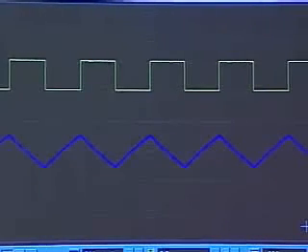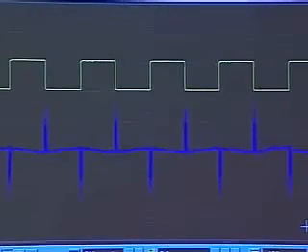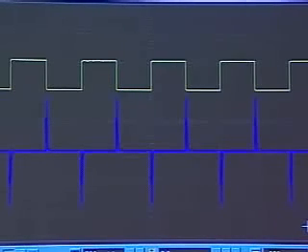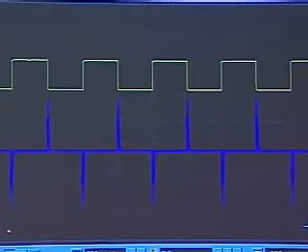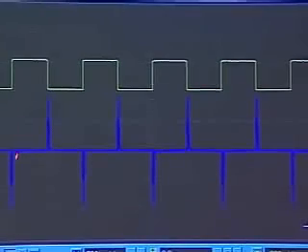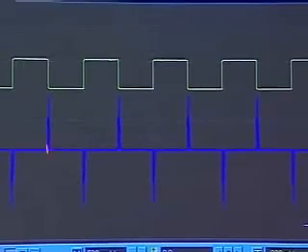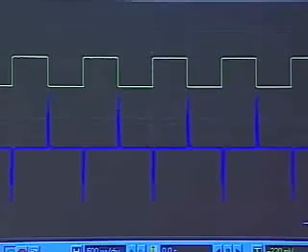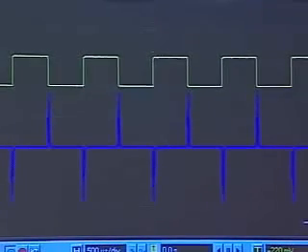And we'll do the same thing for a differentiator. For the differentiator, I input the square wave to this differentiator circuit, and I get this, whenever there's a sharp rise, I get this huge negative spike and a positive spike because of the minus sign. So this is the differentiator circuit when I feed this into the op-amp.